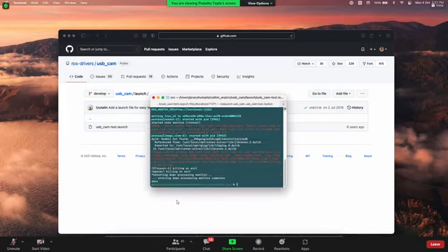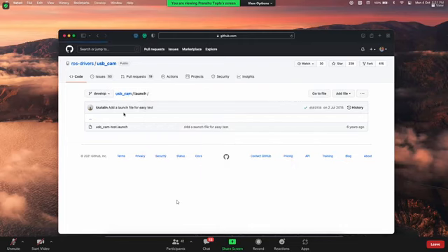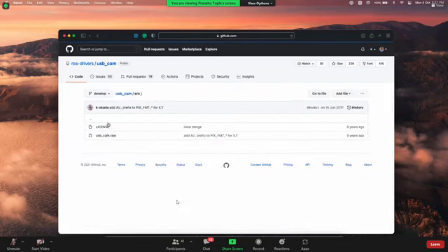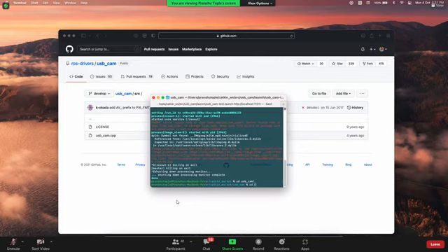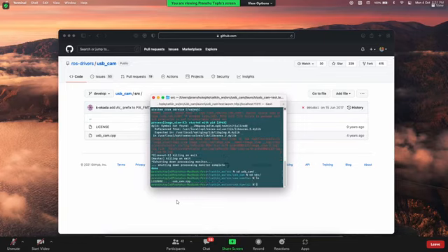Let's check that. If I go into src, these are the source files. These source files need to be executable. So I will go into the package usb_cam and cd src. If I do ls, you can see this is in white in color, which means it is not executable. This is one of the important features of ROS which I like a lot: it tells you what to do. It doesn't only say this is an error, it also gives you the solution.